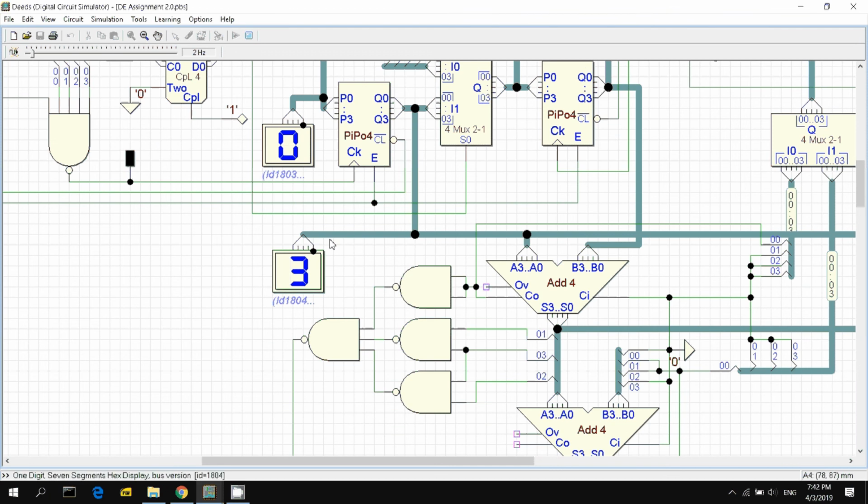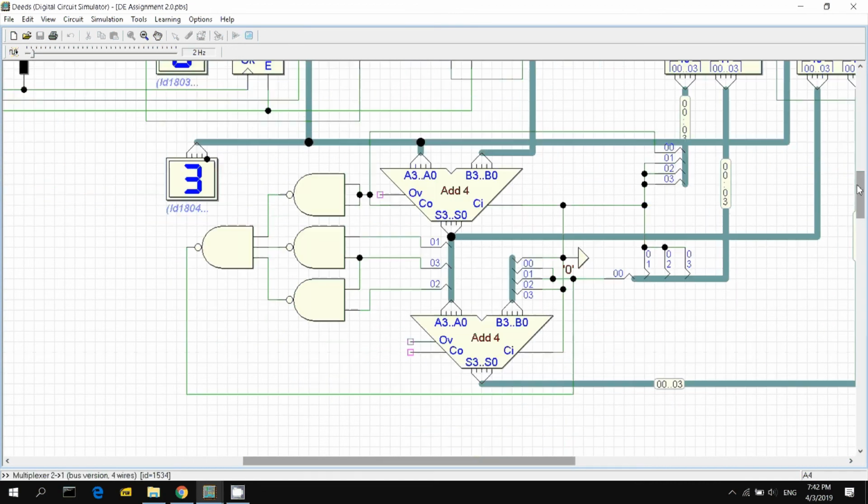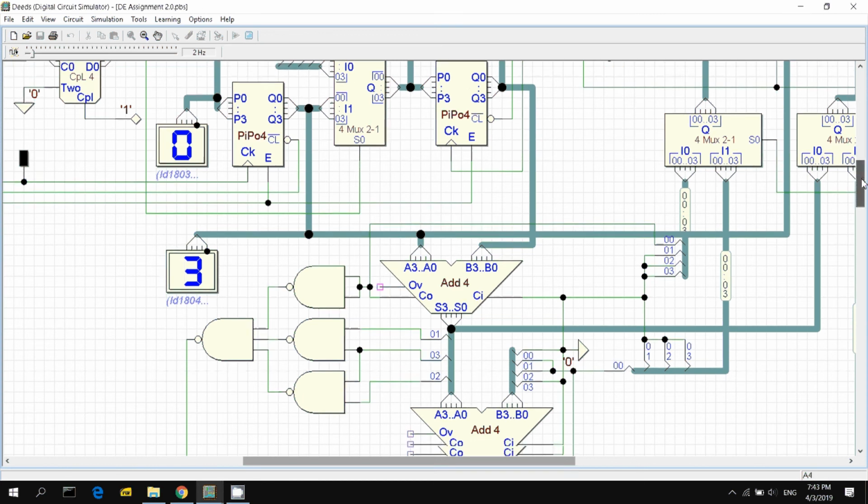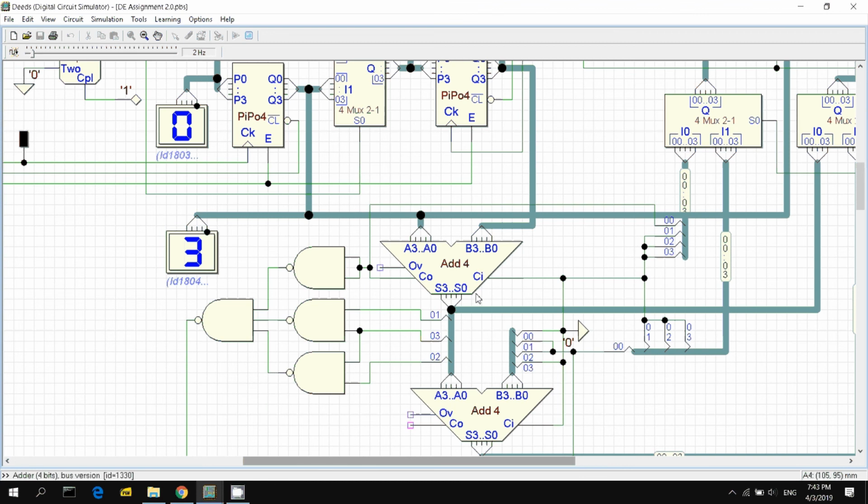In this addition circuit, which we already learned and you can find in our lecture notes, you have 2 full adders, first adder and second adder. The input of the first adder is basically the 2 4-bit numbers, the first number and the second number, which are 5 and 3, and then the output is here. My C in is always 0, because we have no extra carry in, so it's always 0, connected to low level.